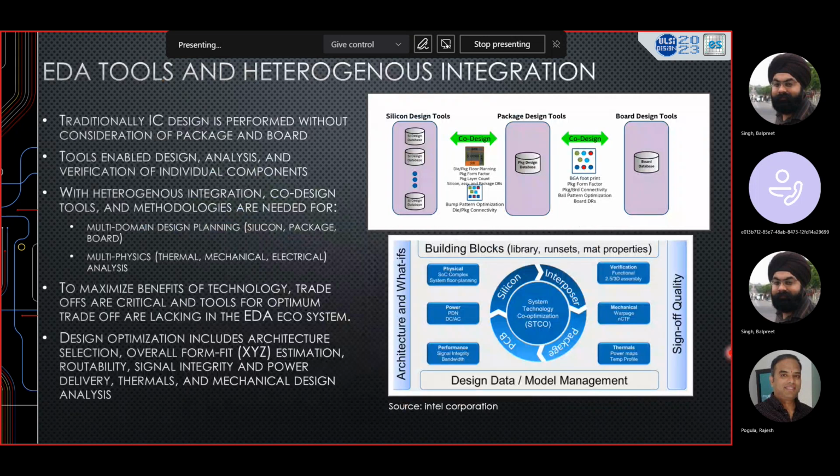That's why EDA tools have to mature, to support this overall ecosystem. Where do we draw the physical cut lines, and what is the design planning? Even floor plan tools probably have to mature. The package person should be able to see which block is where with respect to the whole package-level view. How am I going to connect this block to here? Let's say if I place the block in a different location, I'm not able to route. He should know upfront. So that is the granularity which was not required before. Now it is required, right?